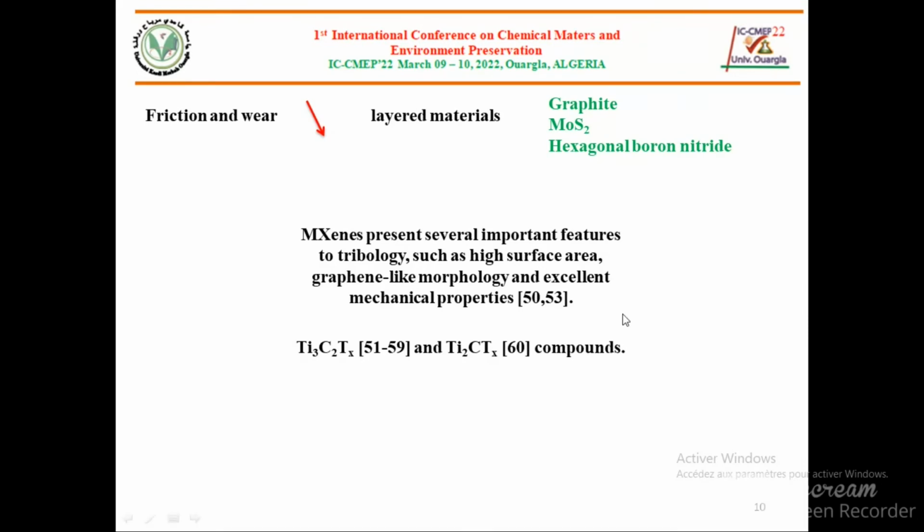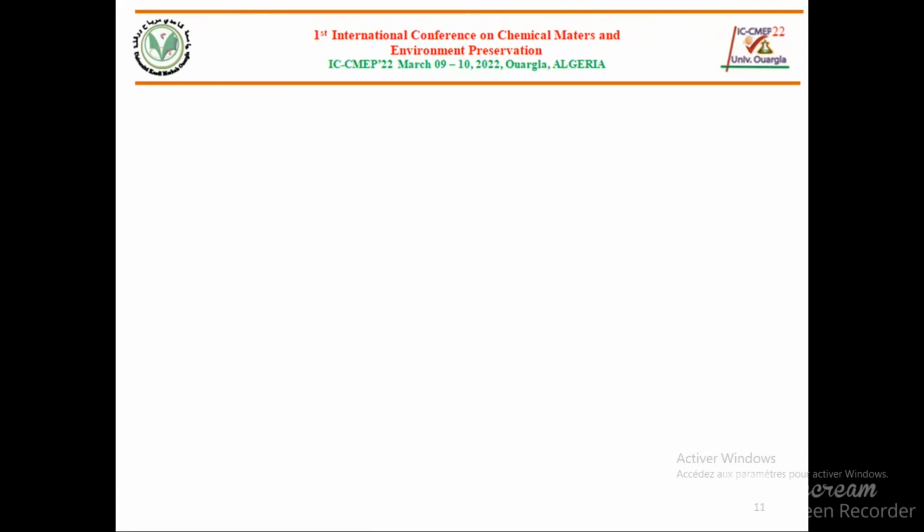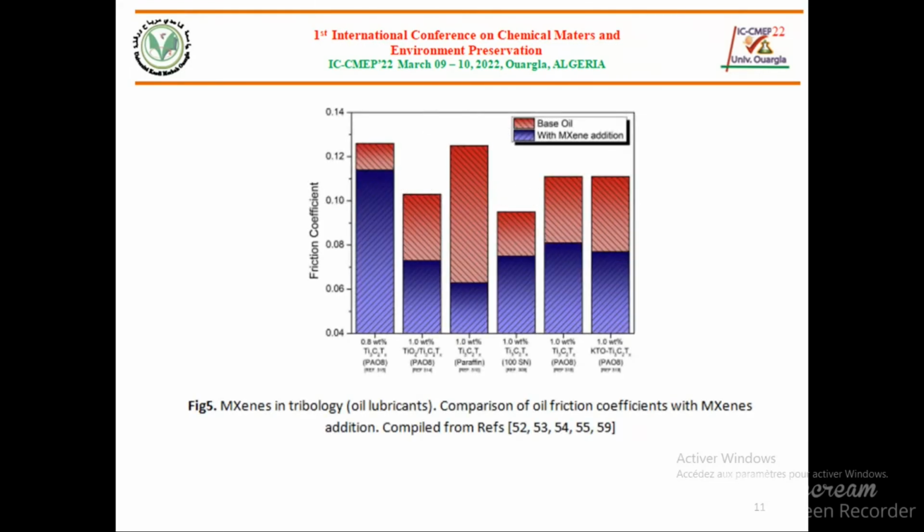The MXenes tribological research has been restricted only to Ti3C2Tx and Ti2CTx compounds. Therefore, it is imperative to study other MXenes in this field. In this application, MXenes were incorporated into oil or polymer matrices. In the former, Ti3C2Tx addition enhanced the oil lubricant properties, significantly reducing the coefficient of friction, as can be seen in this figure.